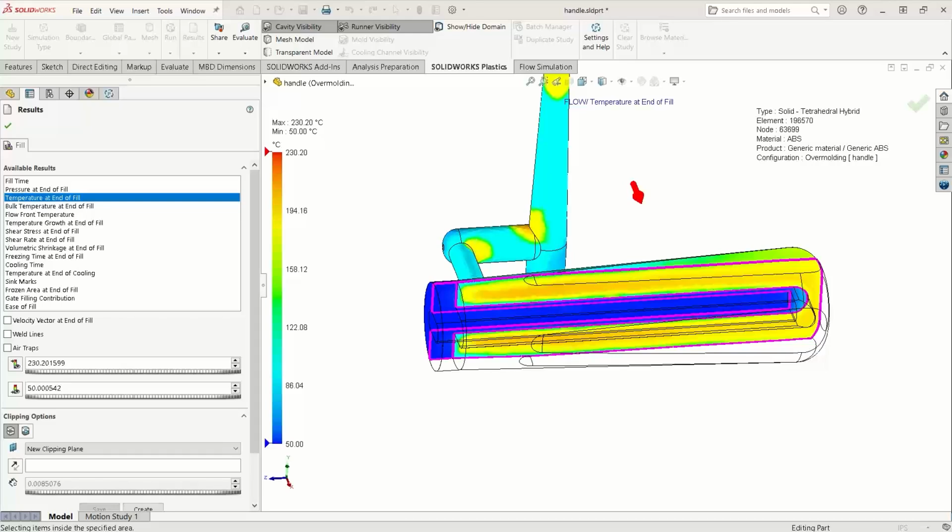So what we've done is we've partnered with a university in Taiwan, where they built 3 different test part geometries, using molds that have been instrumented with pressure and temperature sensors. They molded up to 125 unique combinations of geometry, material, and process conditions, and generated a vast amount of data, which we then used to correlate.